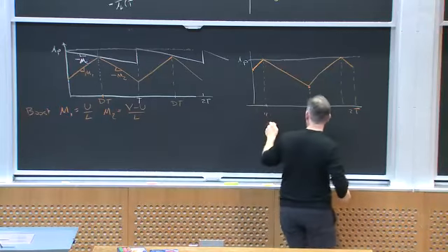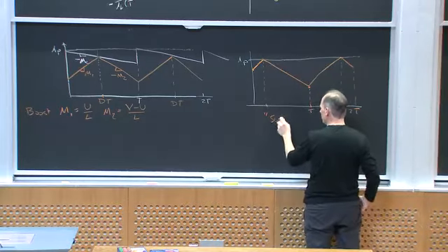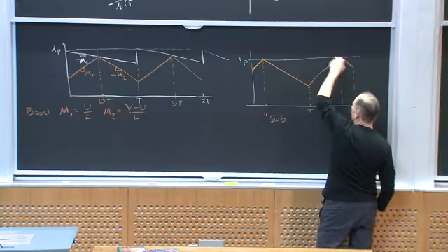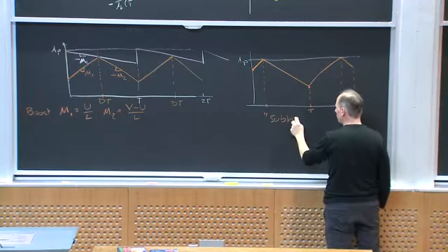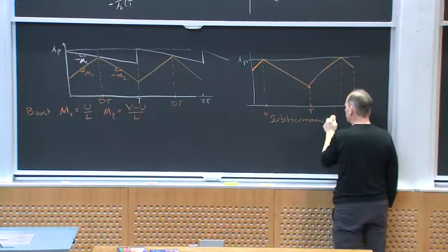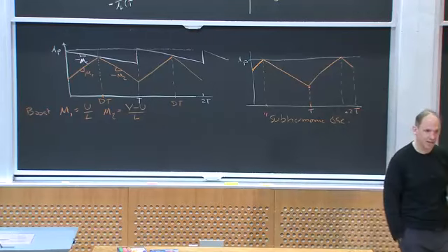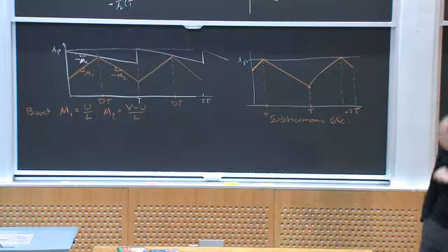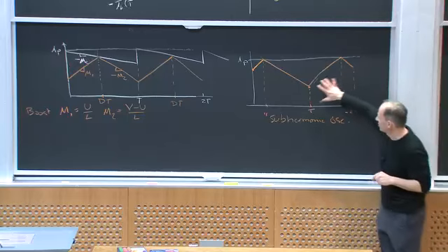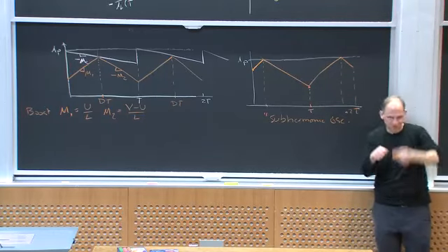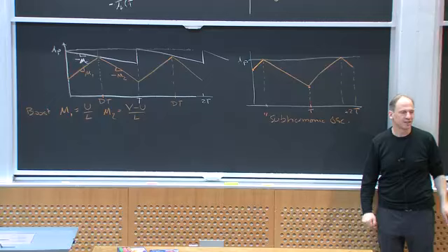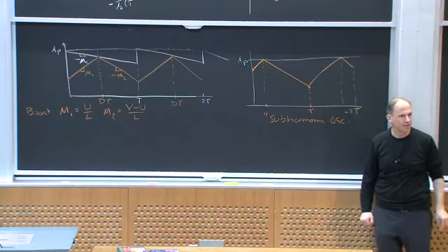This behavior, where it's rippling at a subharmonic, is called a subharmonic oscillation, but as I mentioned, in some cases it can actually be chaotic. Generally, this issue is called the ripple instability. This ripple doesn't settle down into periodic steady state behavior.